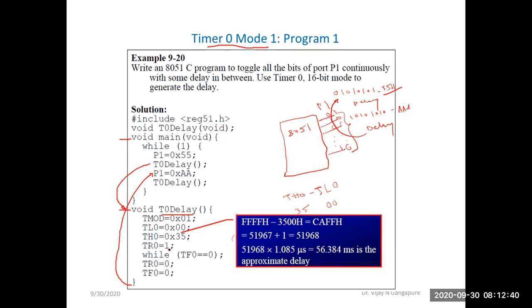Okay, so when timer 0 starts, because we have made the TR0 bit 1, it will start the timer. Means pulses will start reaching the timer registers, and the count in the timer register will start incrementing by 1 due to a single pulse.